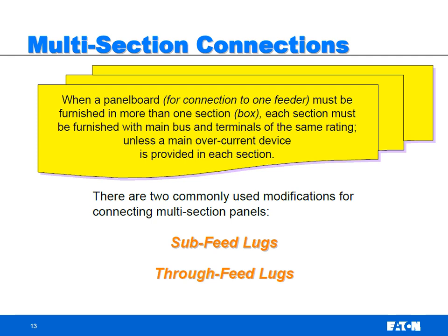But when you're talking normal lighting and appliance or lighting and receptacle panel board that is going to feed a commercial building on the inside, NEC removed that restriction, and the rule now is you can put in as many circuits as a manufacturer can build a panel board. And there's some comments and restrictions that we'll touch on.